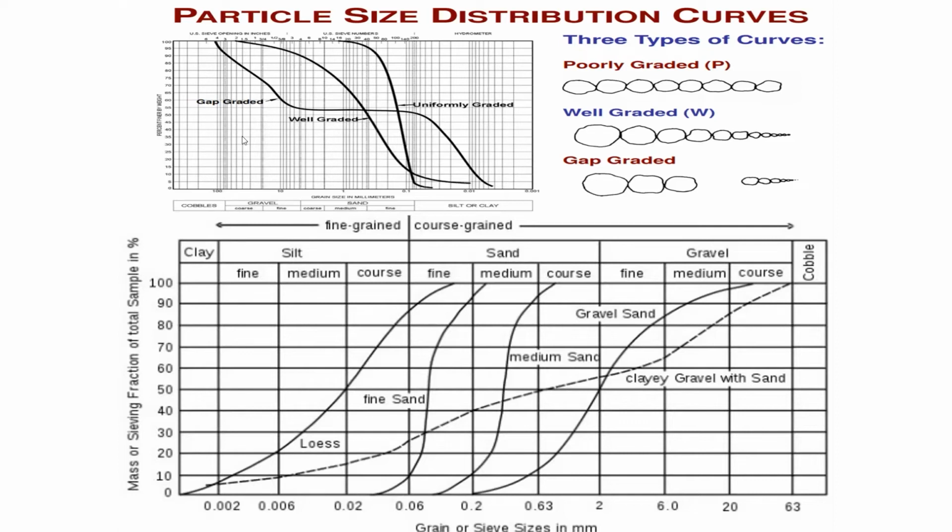Try to understand. See, it is a curve. If I want to classify completely, when you are talking about soil, it is a mixture of clay, silt, sand, and gravel. To understand better, I did an experiment on the complete soil and tried to bifurcate it. In gravel I made 3 classifications: coarse, medium, fine. Sand also coarse, medium, fine, silt coarse, medium, and fine, and clay single.